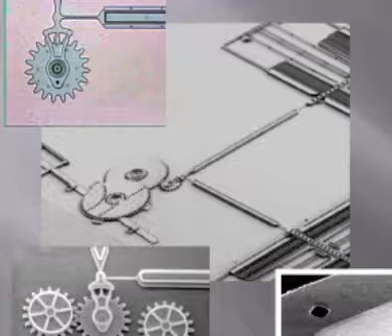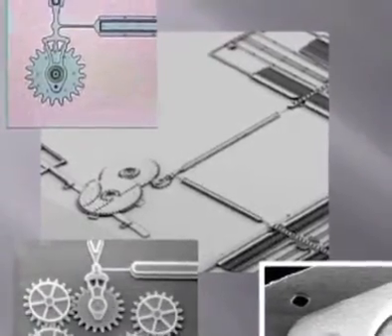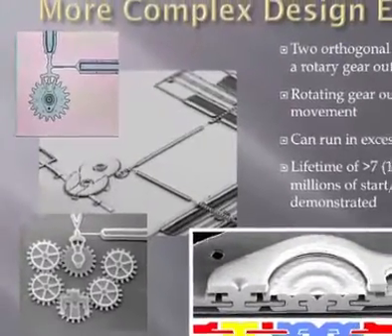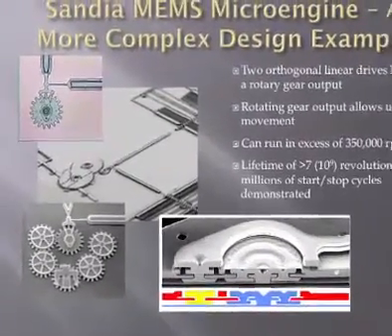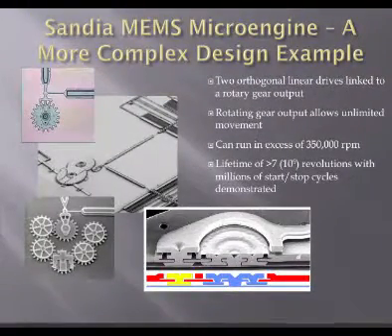And if they're slightly out of frequency, then you'll see this thing. It'll look like a ring oscillating on the screen. And if one frequency is twice of the other, you get a figure 8. If it's 3 times, you get 3 lobes. Okay? So that's by changing the input frequency in X and Y of your electron beam that's inside the cathode ray tube. Same concept here, right? We have one frequency in one leg, another frequency in another, and if you sync it up just right, it'll go in a circle.